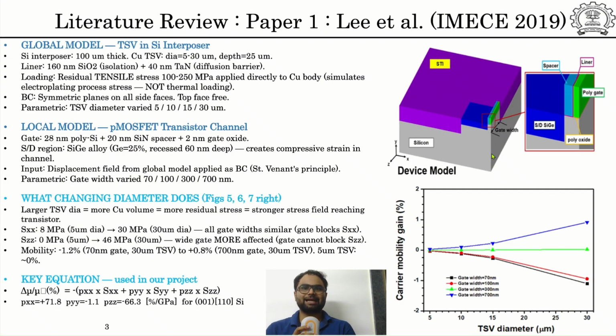Now coming to slide 3, literature review, paper 1. This paper focuses on the device-level impact of TSV stress on PMOSFET. The author used finite element analysis with global-local submodeling to capture the stress distribution at nanoscale. The figure over here shows the layout of a PMOSFET with embedded silicon germanium stressor. The figure helps us understand that the stress is acting directly in the channel region of the transistor. Due to TSV fabrication, residual stress develops which affects the carrier mobility.